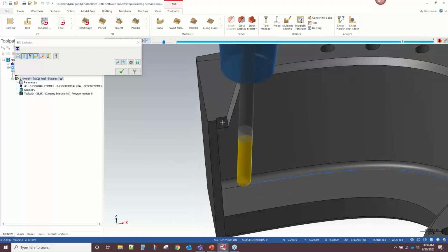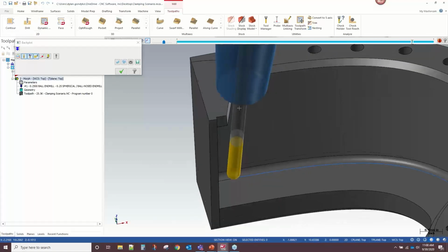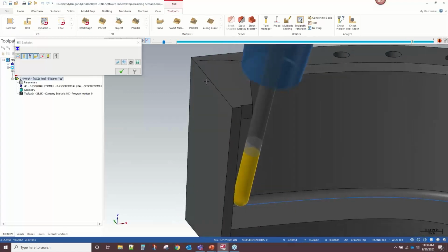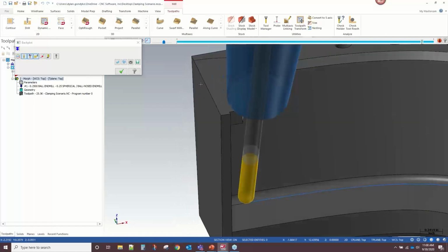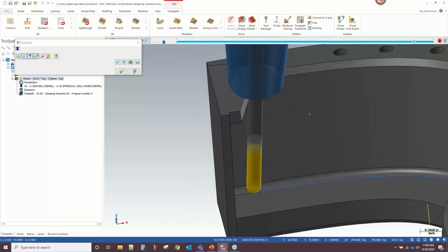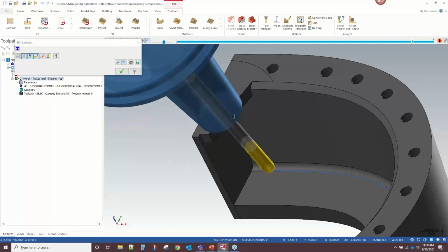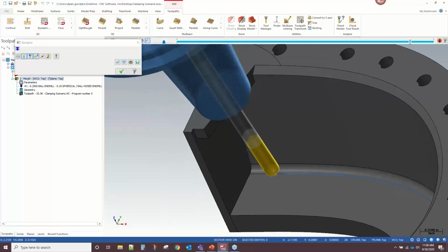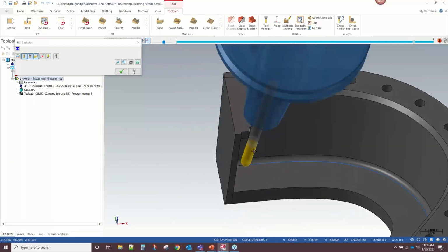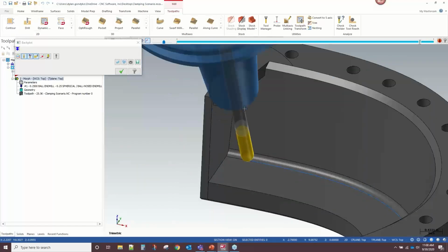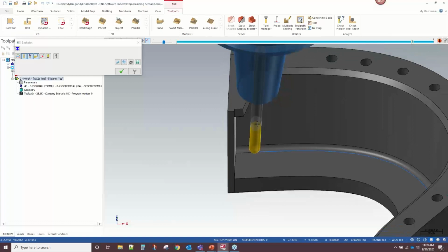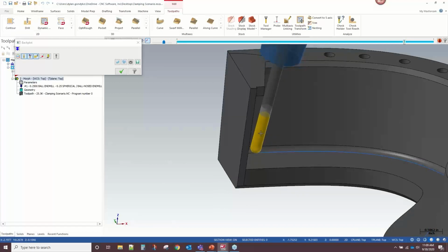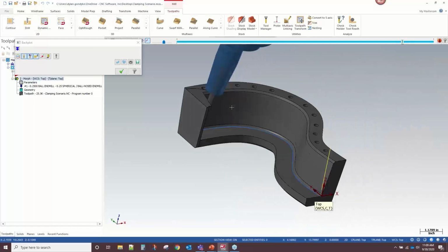So as we come in here, it also does something that I didn't really initially picture in my head. Instead of changing the lead lag angle of the tool, it starts to side tilt around this flange. And I get a lot of tilt motion while the tip of the tool isn't really moving very much. And that's kind of not what I want on this. This might cause scrubbing issues or surface finish issues. I had pictured in my head the tool just feathering out along one direction of tilt to get the rest of that corner.